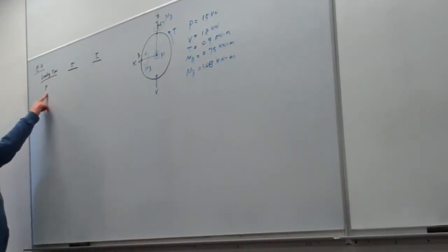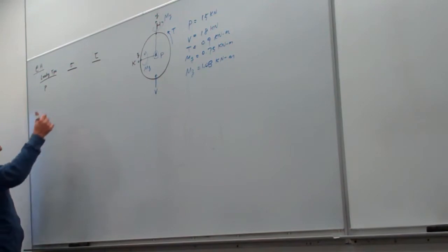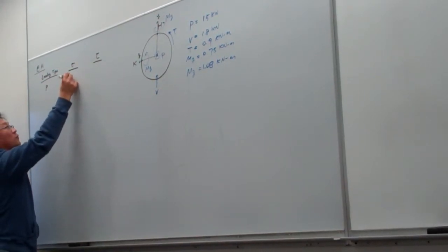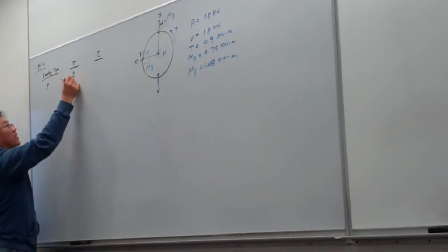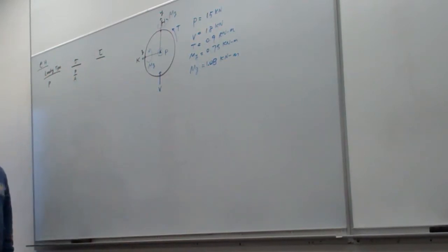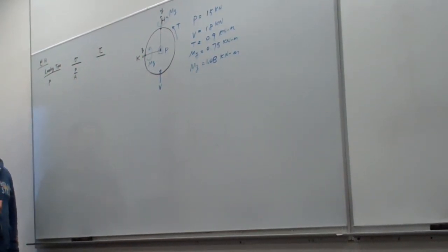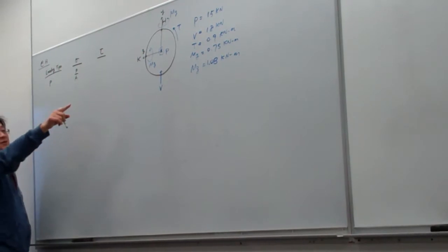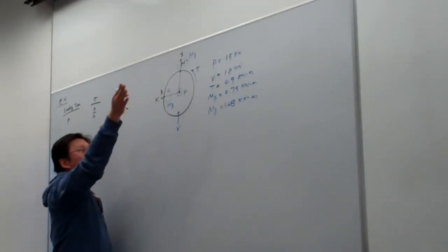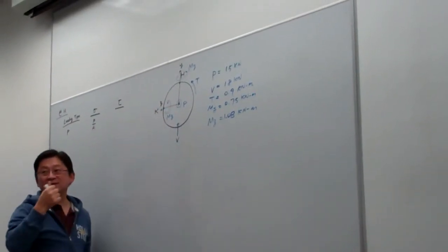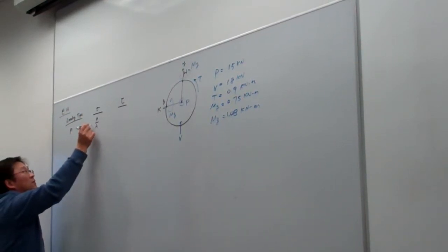Due to the normal loading, and that is our chapter 2, we know that the normal stress will be equal to the magnitude divided by the cross-sectional area, right? For this case, this loading is going into the board, so basically that is compressive. So here we put a minus sign.